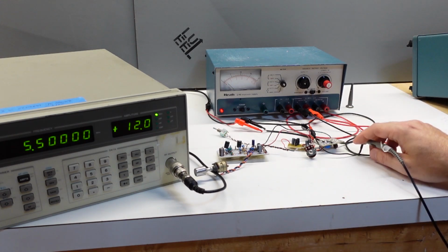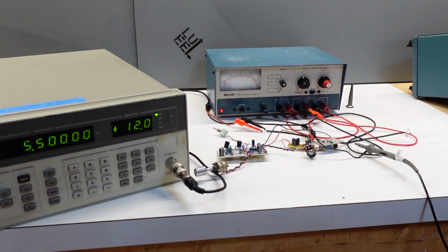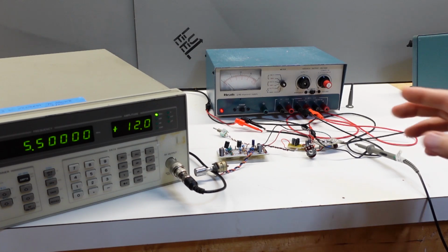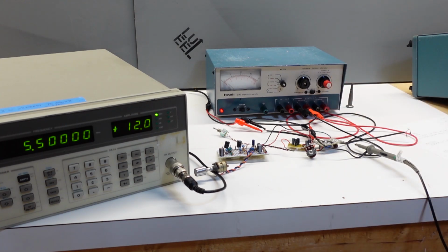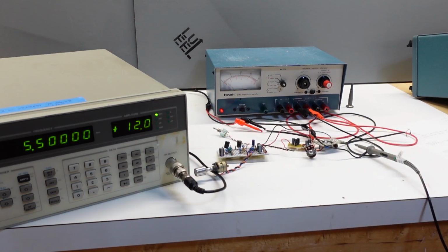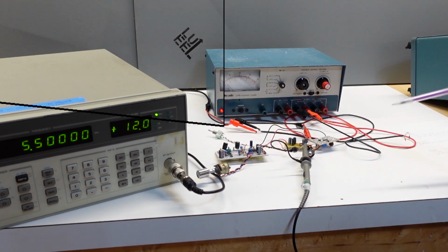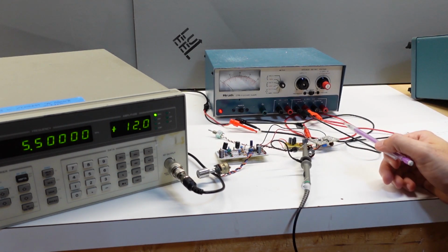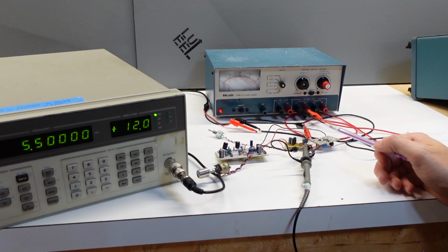And just another comment, this plus 12 dBm I wouldn't read into too much yet, because I've also got a 20 dB pad on this board. I went a little aggressive, not really knowing what I was going to need ultimately from the Arduino, so I can adjust that later. So I would not directly correlate 12 dBm to the power I need from the Arduino and SI5351.